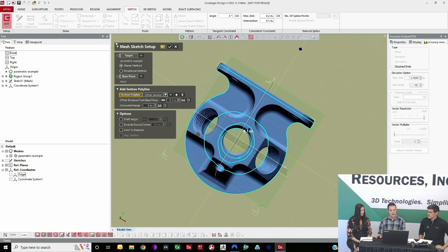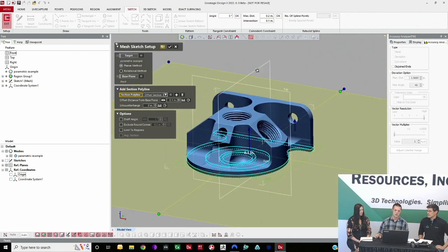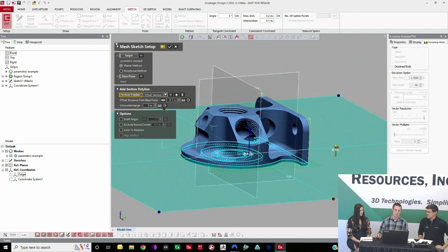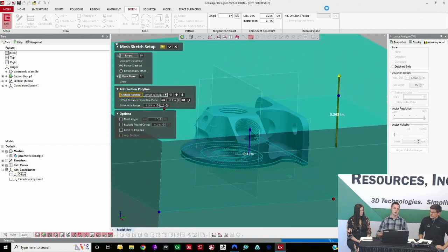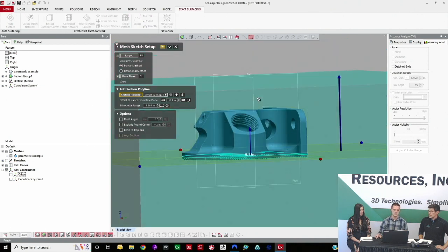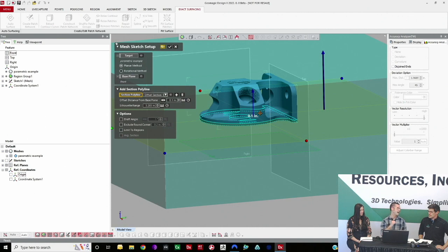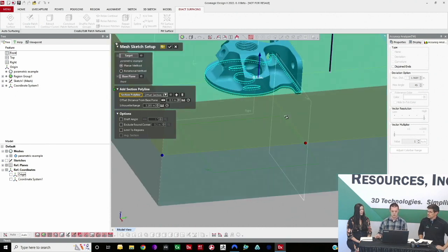If I wanted to be absolutely certain that I was getting the absolute maximum boundary, I can also use what's called a shadow box, which allows me to drag this arrow up. And I have the scan data sitting inside of this volume here. And this is almost like you're shining a flashlight at the part, and so you're getting, for a cast part with draft, right? Yep. You're guaranteed to get the widest point. That's cool. Right. So that's what I'm doing here.